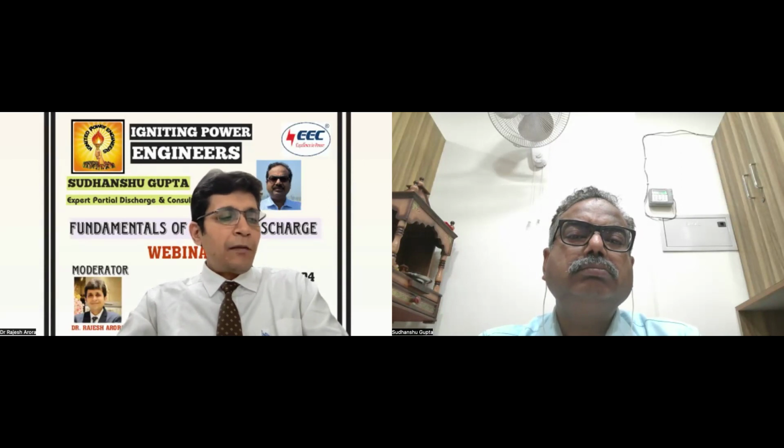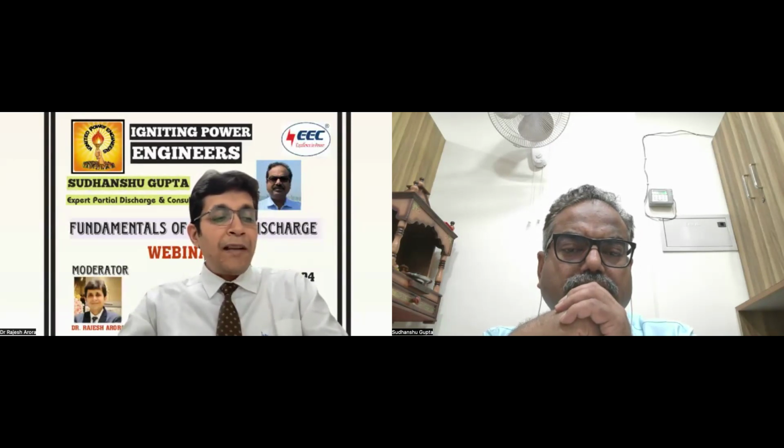Third important is the surface discharge, also known as surface tracking. It is the most destructive type of partial discharge. It is because of contamination and weather conditions, humidity. Last but not the least, the void. That is the internal fault due to defects in the solid insulation of your cables, bushing, transformer, GIS, etc. It is highly destructive to insulation and will typically continue to expand until it causes the complete failure of my